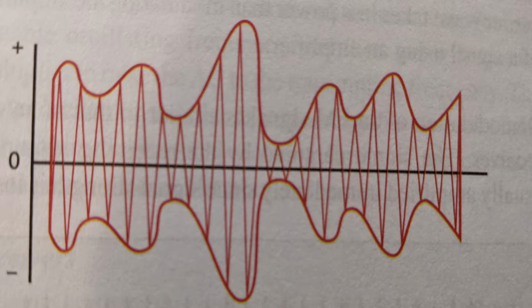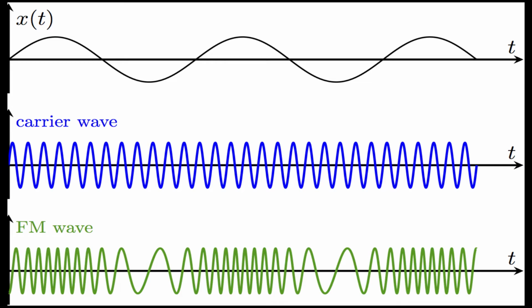Frequency modulation, or FM. Frequency modulation is widely considered to be superior to AM for carrying and deciphering information on radio waves. The information signal alters the frequency of the carrier wave in proportion to the strength of the signal. FM bandwidth is greater than AM bandwidth. This is overshadowed by the ease with which noise and static can be removed from an FM signal. FM has a steady current flow and requires less power to produce.